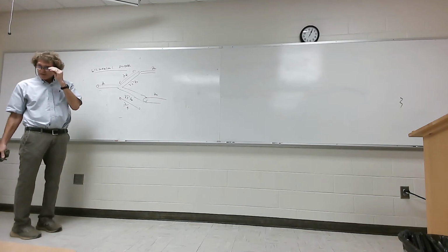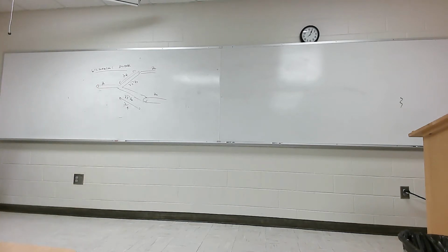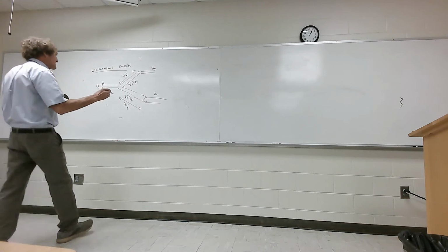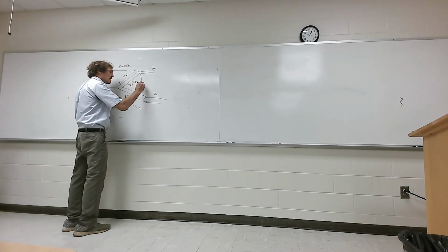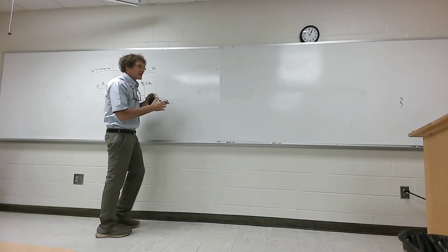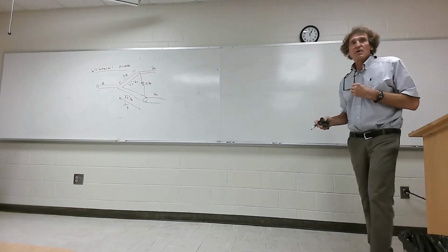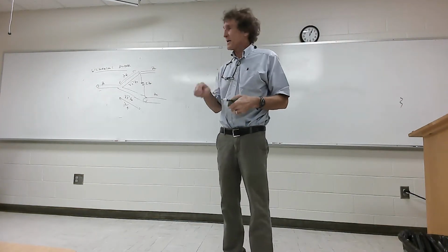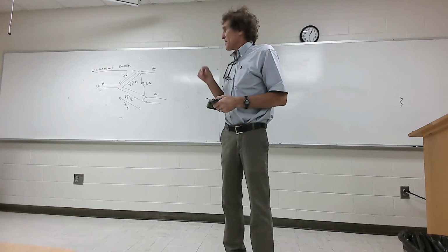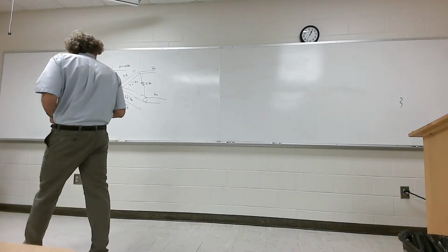Now, anybody want to take a guess why he used a quarter wavelength there? Do you remember a quarter wavelength transform? By the way, there's one other thing too. There is actually a resistance here that will be 2 times Z0. He'll show you that resistor, sometimes they don't. Ideally, there'll be no current that flows there, I'm just telling you, ideally there won't be. And they're both to the upper pin of those things, to the positive line.